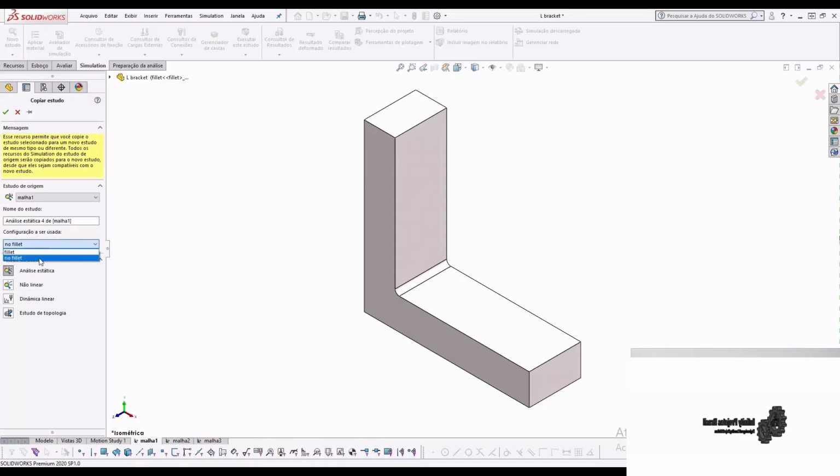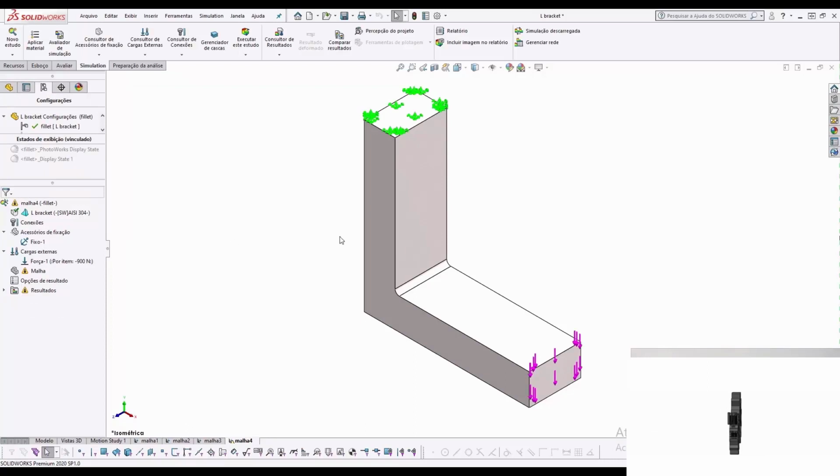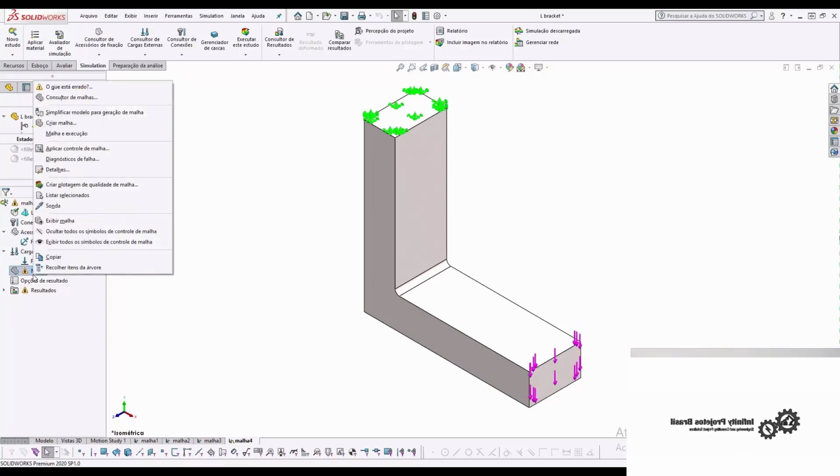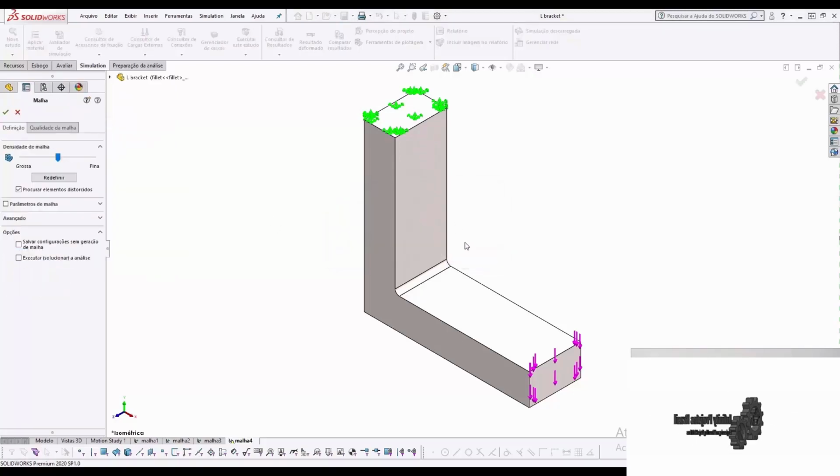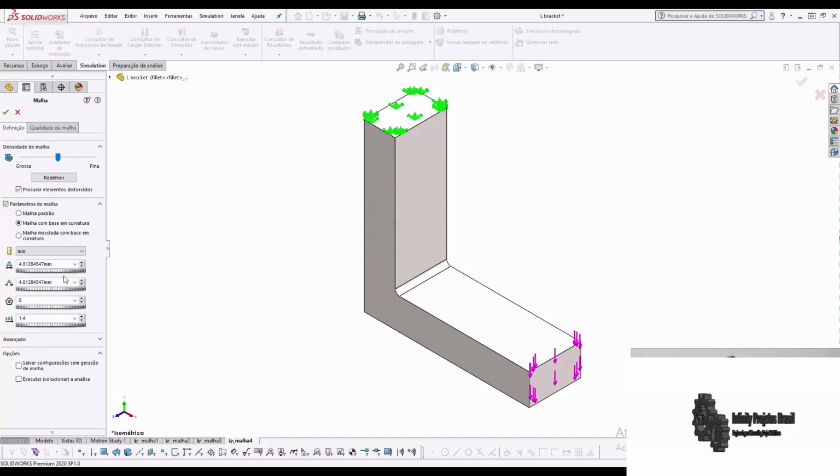But one thing we can observe here in this region of the mesh is that the results are not symmetrical, they are very irregular. This is a problem because we have not refined our mesh. Here the fillet results were between 62 and 63, in the case that it was already refined. Even with the fillet here it gave a very regular result. We can use some mesh control techniques to try to improve this region.